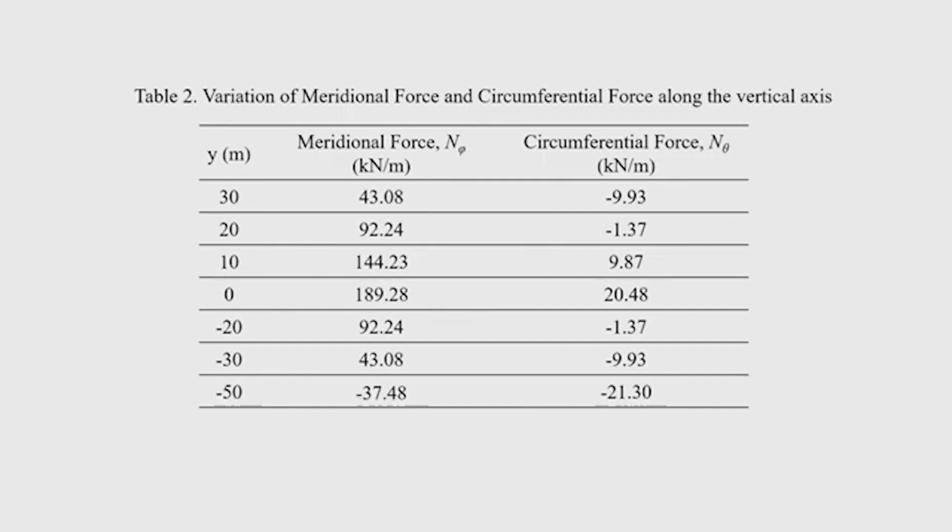Suppose you know the force per unit length, then the maximum force per unit length, that is of tensile nature, divided by permissible stress in tension of steel, that is taken as 230 Newton per mm square, will give you the area of steel per meter length, in millimeter square per meter length.